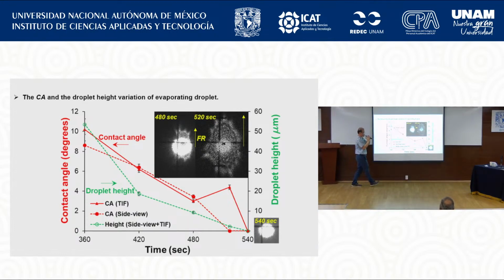Okay, that causes this fringe radius increase, and correspondingly, the contact angle increase at the end of dry out, which is now thought to be caused by non-uniform evaporation flux, which is not analyzed in detail yet, okay? Which needs to be studied further, okay?